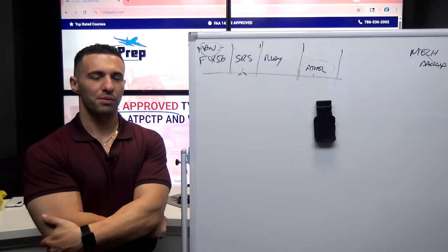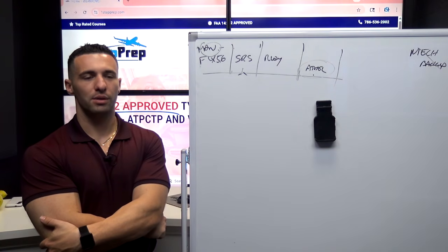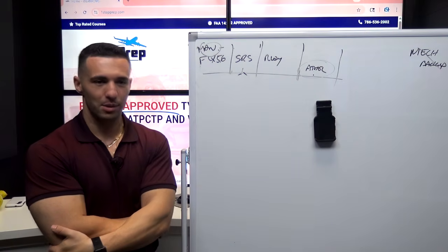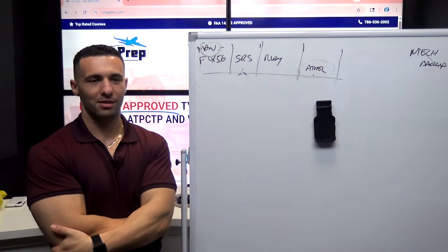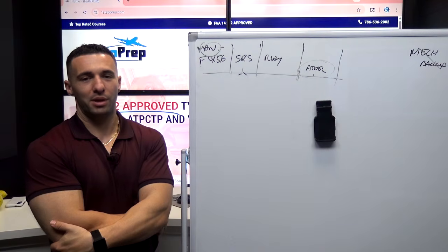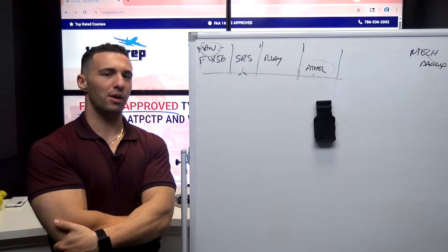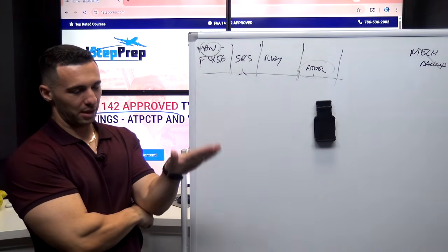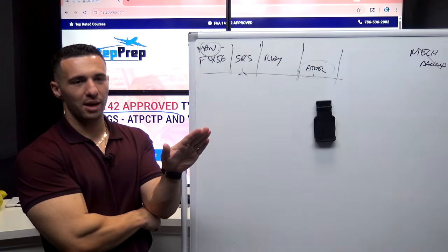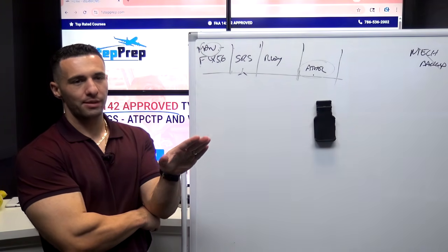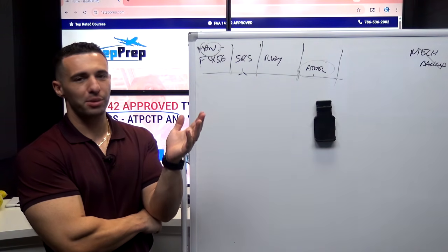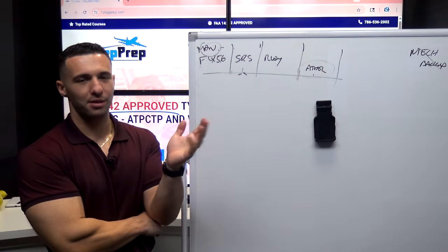I don't have any problem with flying a little bit below the configuration speed. You could technically go all the way down. Let me just simplify my answer and say technically yes. You could put it in flaps 1, not fly S speed, and go down to 170. I don't particularly do that. It sits the deck angle too high. It's uncomfortable. You're still going to have all the protections. You can still pull G's and everything.